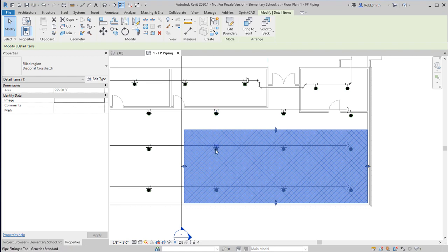This looks like it's about halfway across, about halfway between, if not a little bit under, and I'm looking at 955 square feet. So these 6 sprinklers satisfy the 900 square feet. And if you remember from what we saw, that 5 sprinklers was the minimum. We have 6, so we're good in that regard.